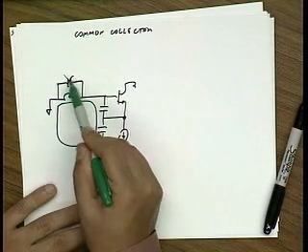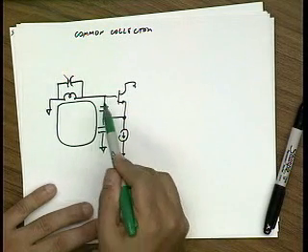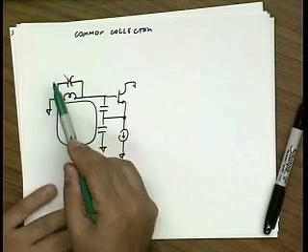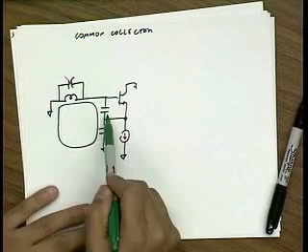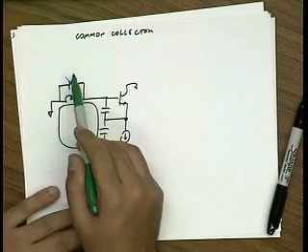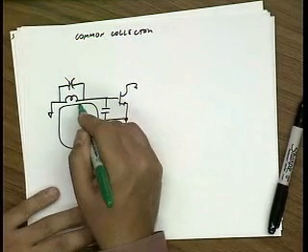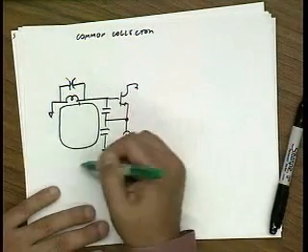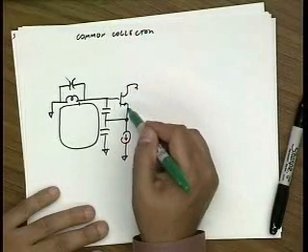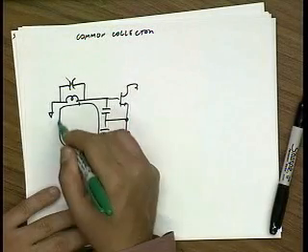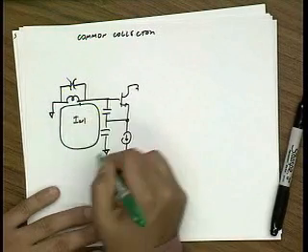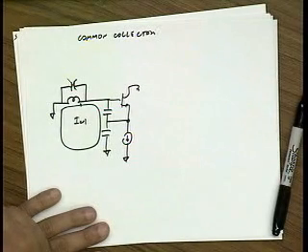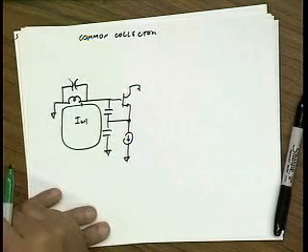In fact, this capacitor can just be moved in parallel with these capacitors, and you can think of this as one net capacitor. So there's no need to put an explicit capacitor here. You can just make these capacitors bigger to make the total tank work. So you get rid of this extra component, and then the circuit becomes very simple to think about, because again, under a high Q assumption, this tank current is much larger than the current that's being injected by this transistor, and so for all purposes, I omega 1 flows through here and produces an input voltage and an output voltage. Okay? So same kind of analysis we can apply to this oscillator.